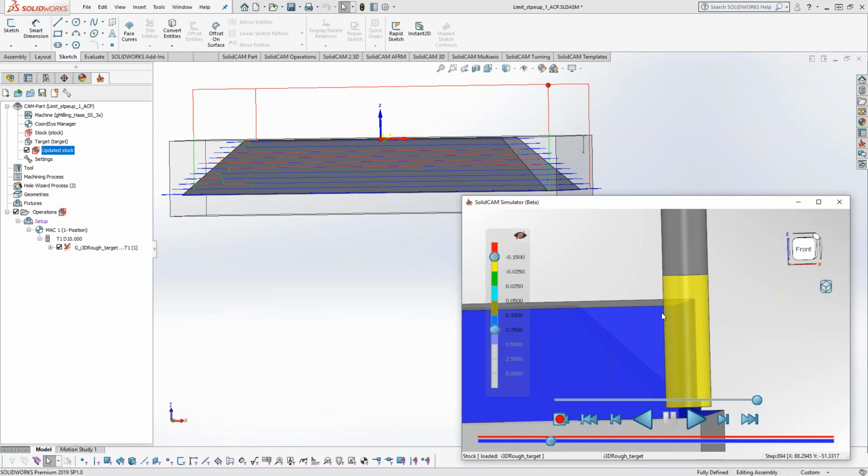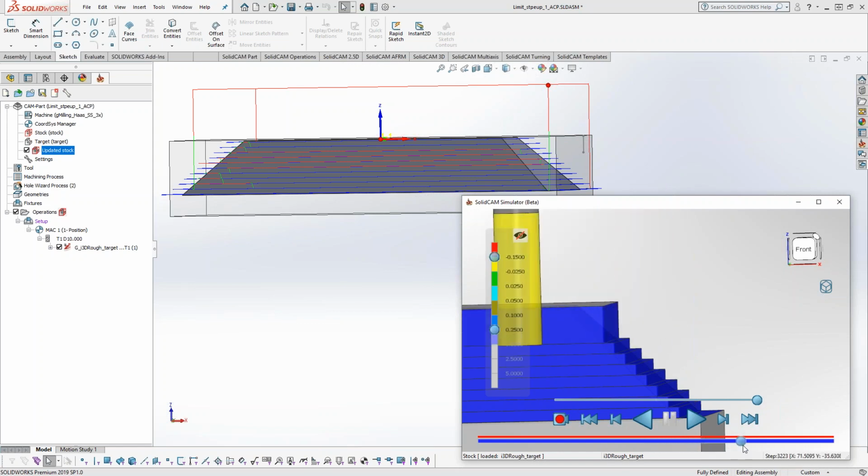And this is the best for cutting, to get the most amount of material engaged with the tool as possible. So as we step up this tapered rectangle, the depth of cut is getting less and less as we go along. And at some point we come all the way up to, let's say, the top, and you can see we have very little engagement with the tool axially. And this is where we get vibrations.